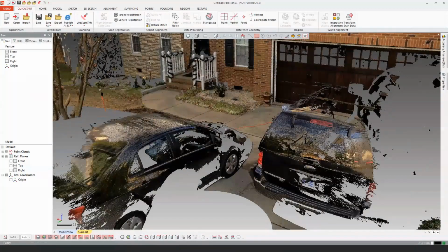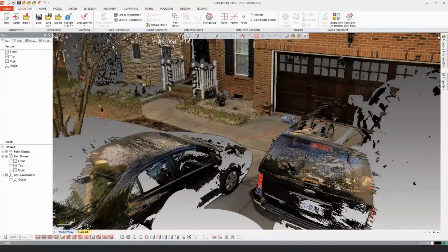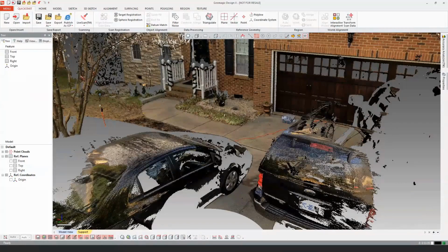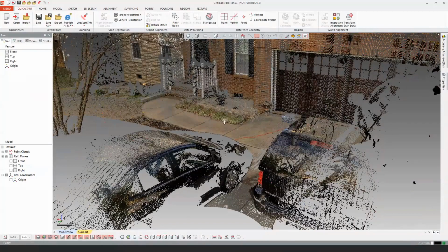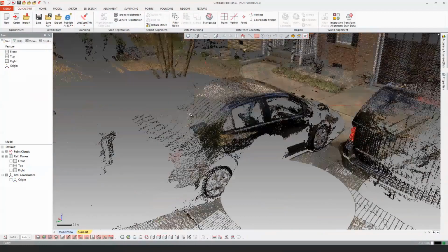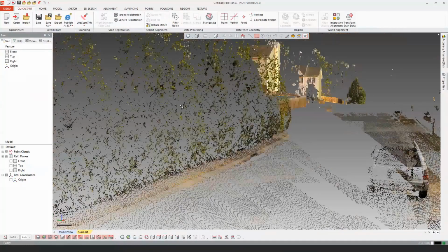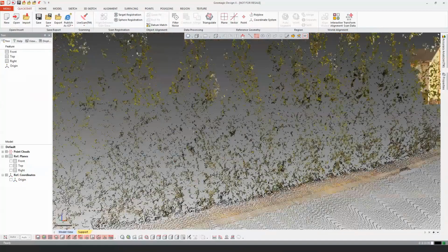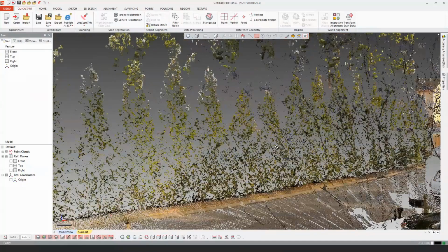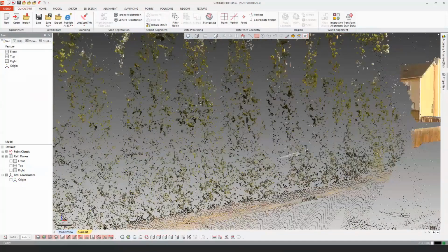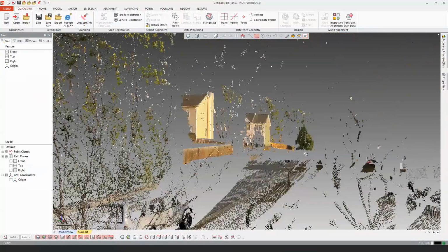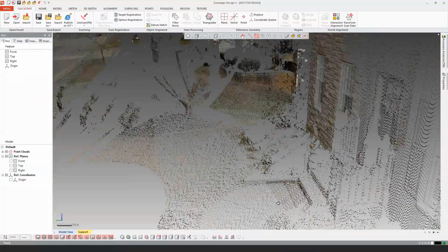And there are some right-click options here that you can see in our menu. There's a couple of different ways to move around and fly through your scene. Right now, if I hit Shift, I'm doing essentially an up and down, left and right. So this is sort of a pan through my scene. Rotate behaves a little bit differently. Now instead of rotating the model, I'm rotating a camera view. And as I zoom in and out, again, I'm flying back and forth. And then I can also, with the Control key, do a full pan fly around, which is nice. So I can really get a feel for the lay of the land of what's going on with my scan data.